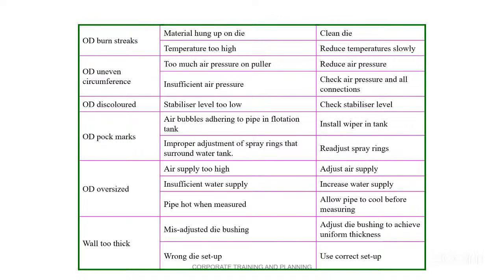You have to install the wiper in a tank, or you have to adjust the spray rings again. Spray rings are there, you have to adjust them properly. Otherwise, these pockmarks are always on the pipe.